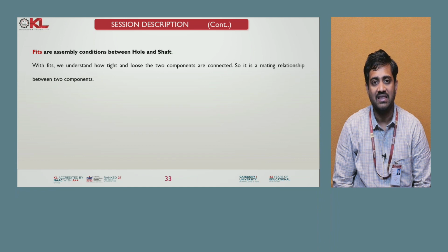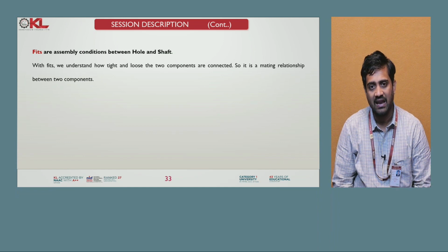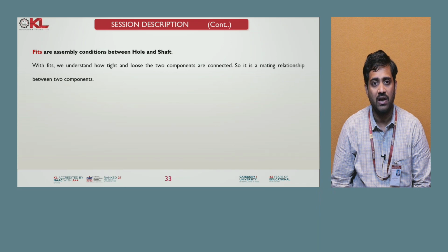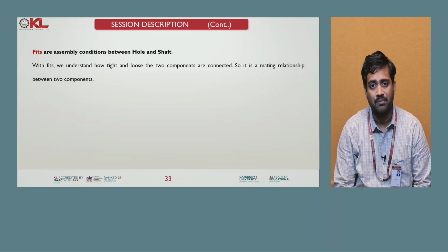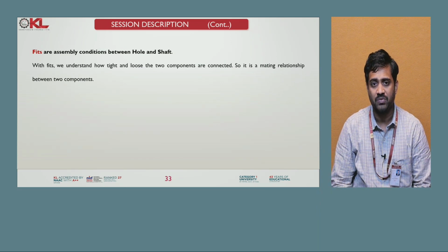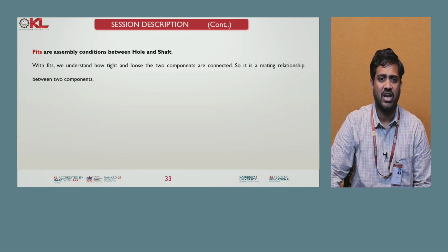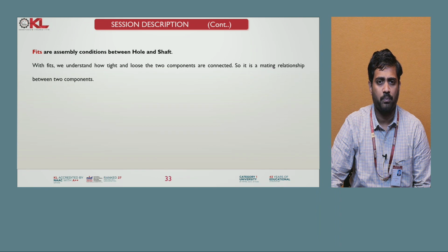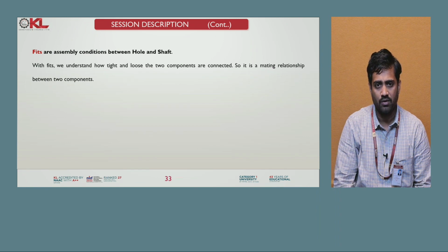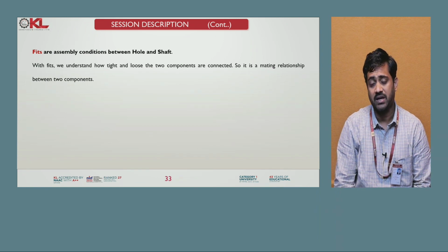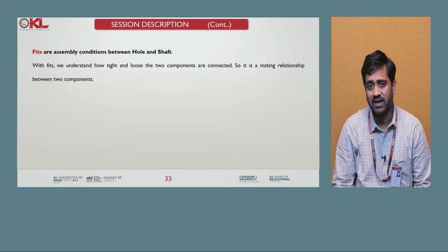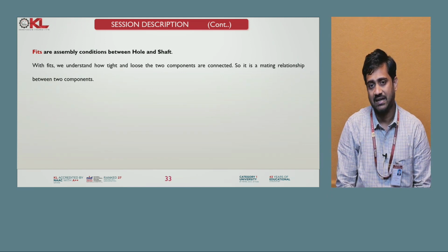Whenever the clearance is nil, the shaft can't move freely. To move the shaft we need to apply some extra pressure or force, which is not required when there is minimum clearance.